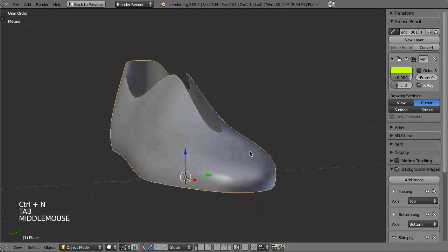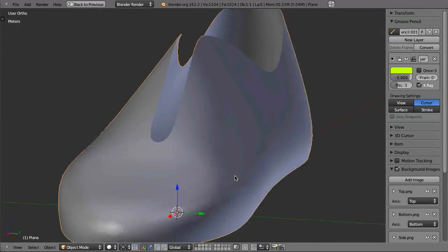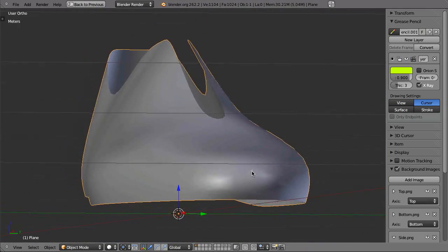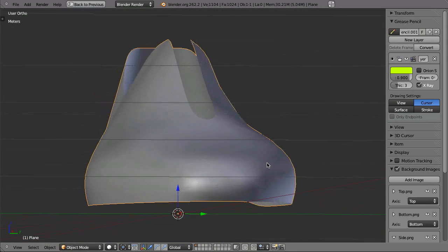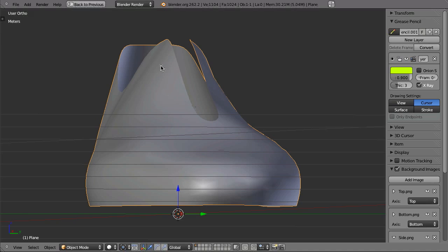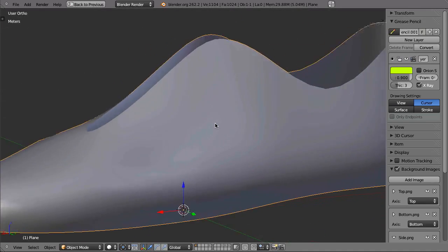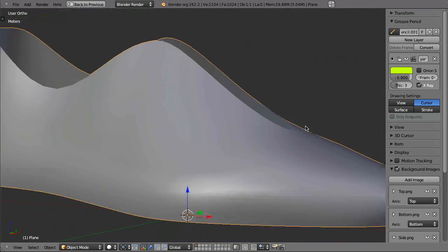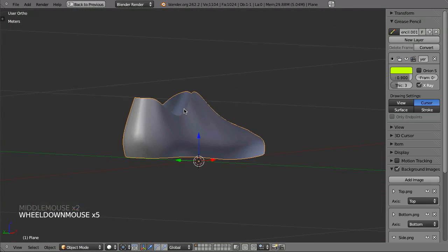And also a nice tip, and again, why you should work really with a low polygon model: move your mesh very often in shaded view, and then pay attention to, for example, as you can see, here is a shadow line, there's a shadow line, and try to spot if there are any dents or depressions inside your mesh you might need to get rid of. Okay.